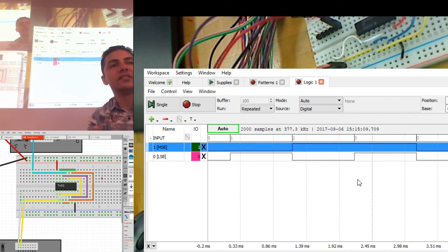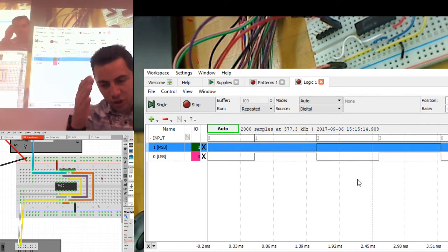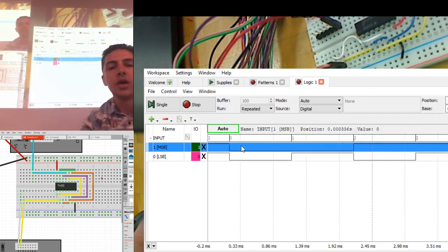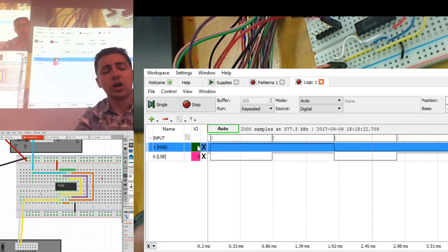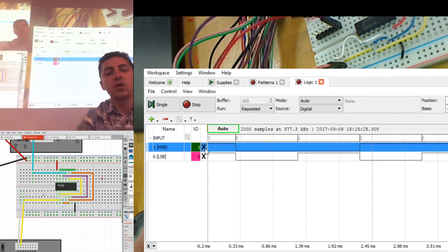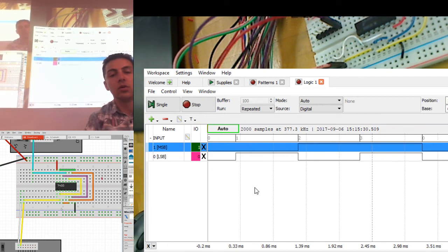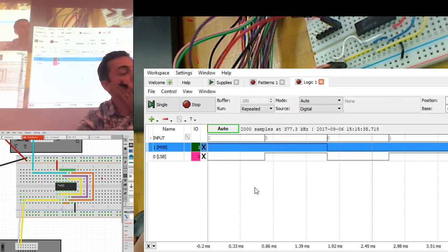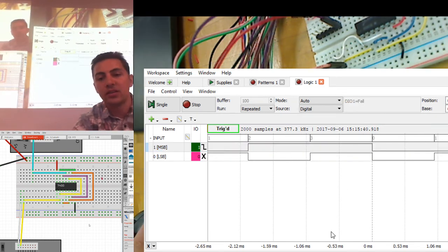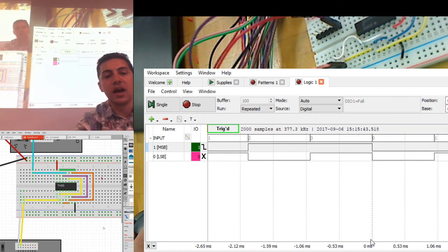It's just showing you whatever's on screen at that time. What we can do, however, is synchronize it. It would be nice if we could get it to show 0 right in the center. Every time we show a 0, that's what we want to trigger. So these items right here are shown as X's, meaning don't cares. If you click on one of them, you can say, hey, only trigger when this most significant bit goes from a 1 to a 0, which is called a falling edge. And all of a sudden, just like that, time 0, right there, is where this guy has a falling edge.